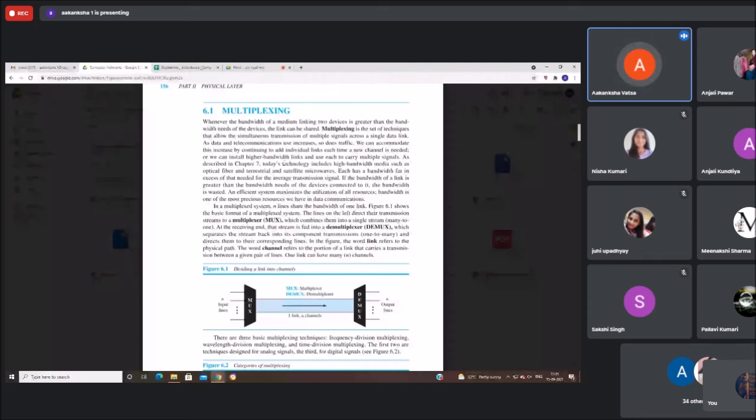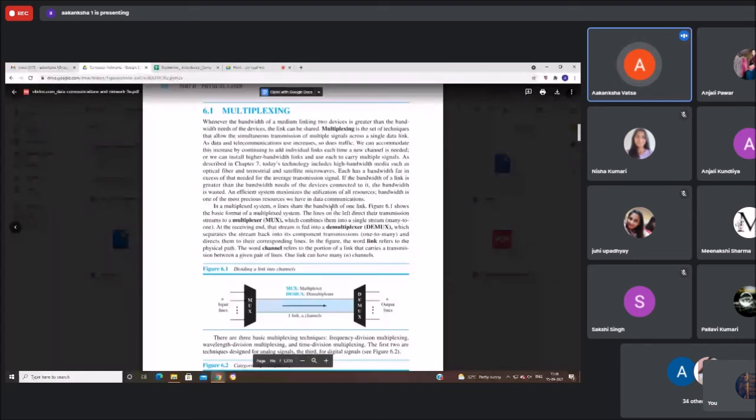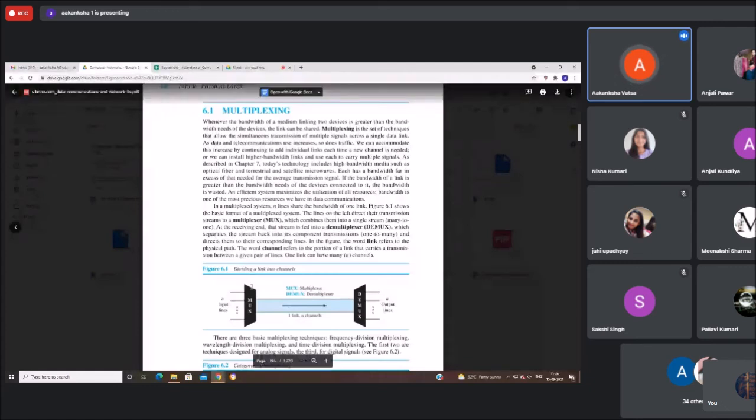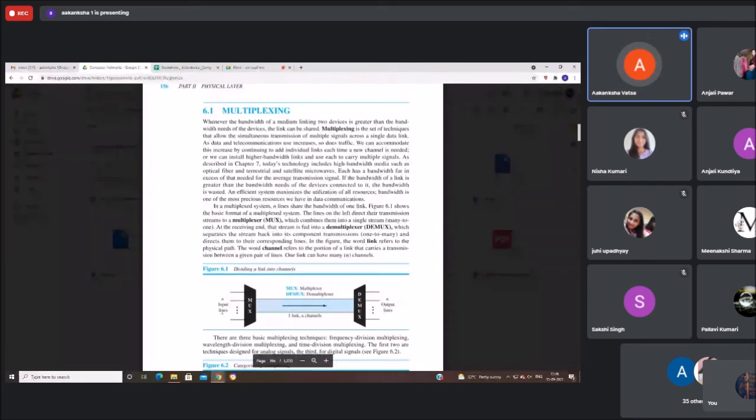Normally in multiplexing, we are using the entire capacity of the single link between the source and the destination, and we are sharing the channel. In multiplexing, we use 2 types of devices over the channels and links. At the sending side, we have n devices which need to be multiplexed and will share the same channel. So we need a multiplexer, known as n×1, which has n input lines and devices connected to it, and the data from those n devices will be sent over the same carrier channel, over only one link, to the demultiplexer at the receiving side.